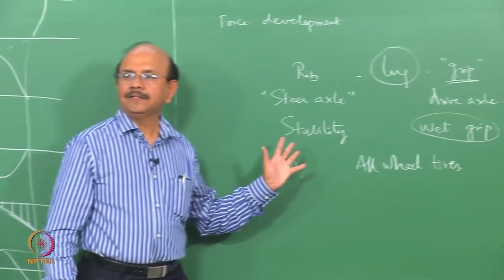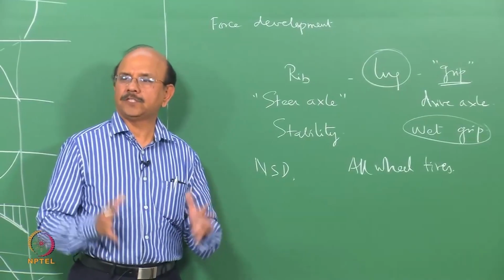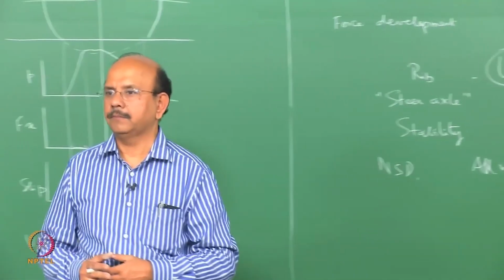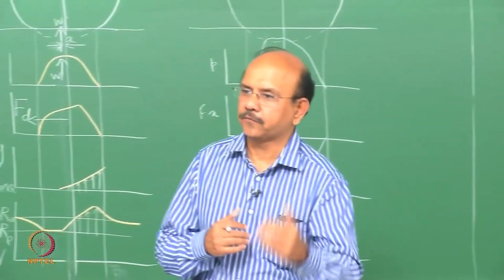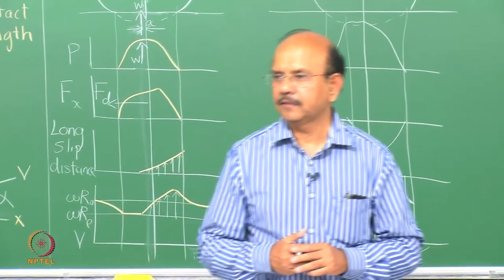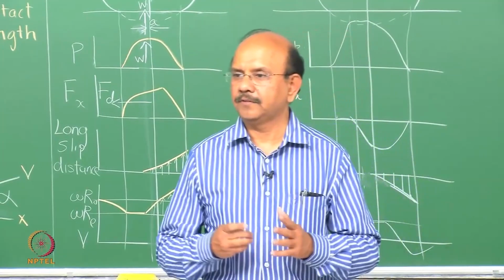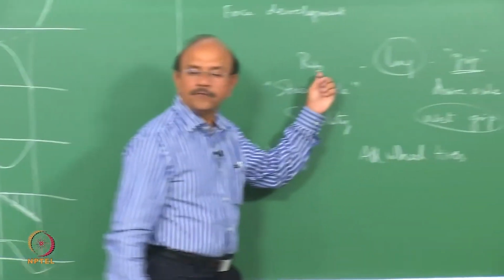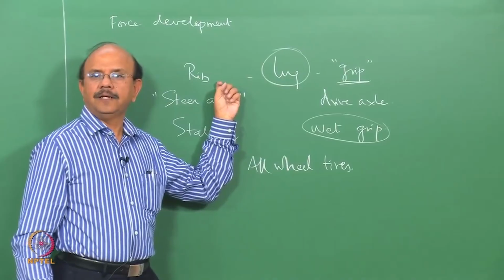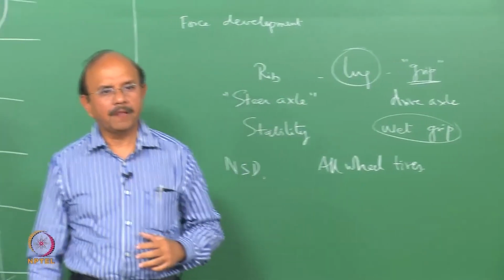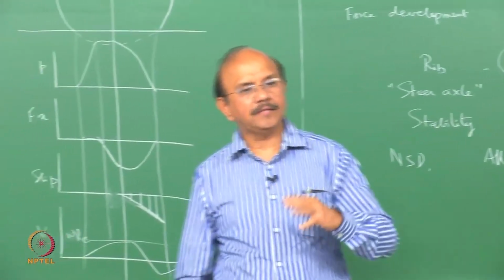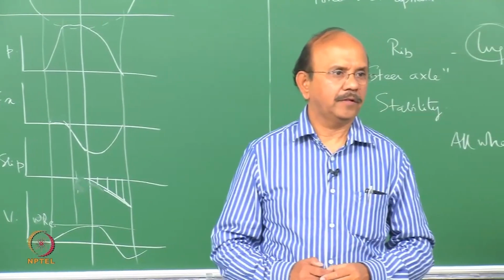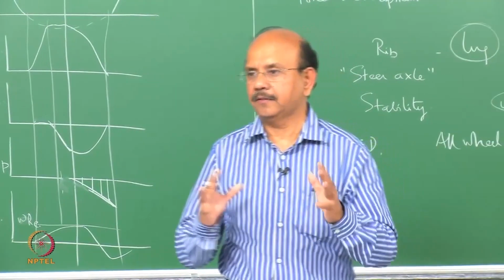In fact, the vehicle parameters, which we would call suspension parameters, such as toe and camber, as well as what is called the axis of thrust, which we'll define later, have an important effect on the wear of these rib tires, and these factors usually make the tire not wear uniformly. There would be an uneven wear in the tire.